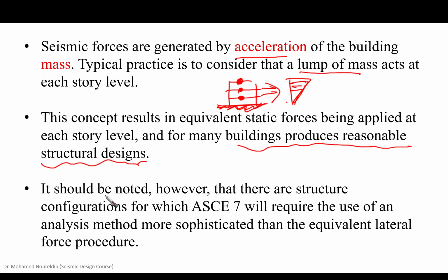It should be noted, however, that there are structure configurations for which ASCE 7 will require the use of an analysis method more sophisticated than the equivalent lateral force procedure. Yes, we have response spectrum, as we are going to explain later. We have the time history approach, time stepping. We call it time stepping or time history, and we have nonlinear time history response analysis. Okay, for special structures, which exceed a certain limit in height or exceed the regular conditions stipulated by the guideline.